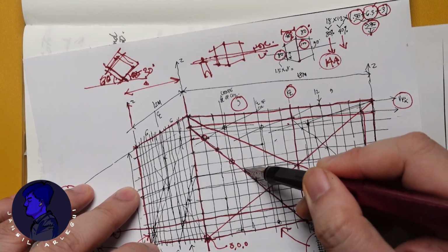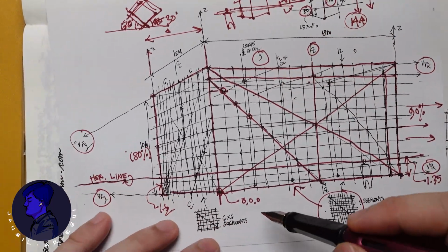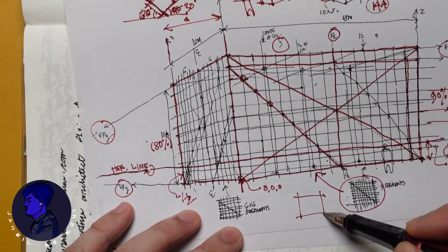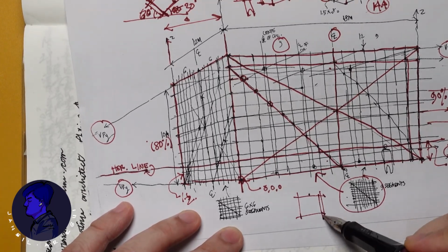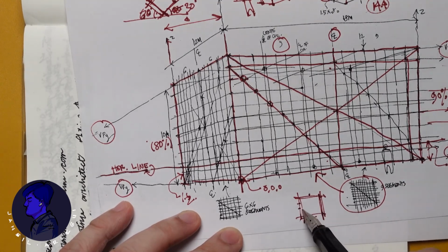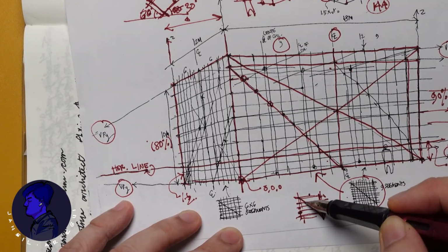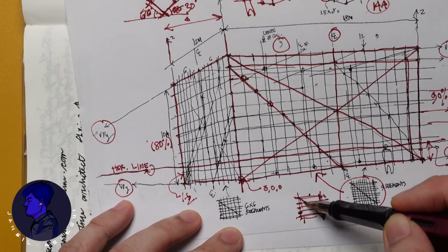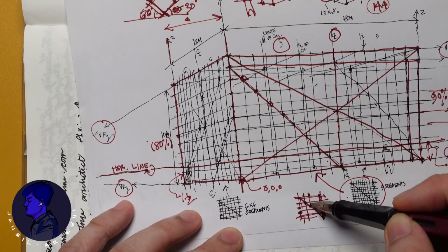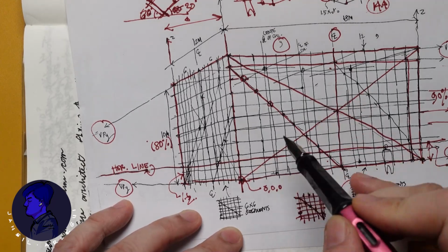So in order for you to get that accuracy, you can do this by segmenting. What I did here is, if we do this in orthographic, if I want to subdivide this into 4 equal parts, first I measure where the lines are going to be, the horizon lines. I draw the horizon line, I draw a diagonal, and where the diagonal and the horizon line intersect, that's where I draw my vertical. So it's the same principle when you're trying to draw it in perspective.